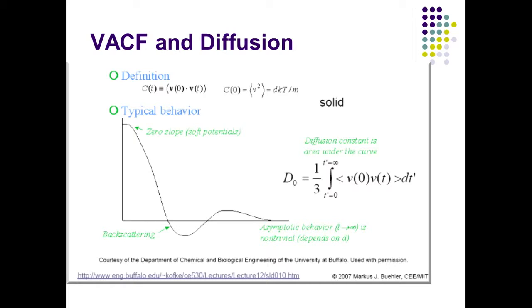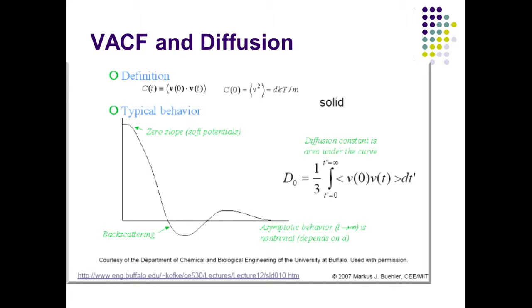As we said, in a solid there is some diffusion of the atoms, but around their lattice structure. So, there is a lattice position, and if you look at X-ray diffraction of the material, you will see particles at particular locations. But you know that at any temperature, given the vibrational frequency, the atom is moving around its central position, and that is the local diffusion. So, you can also calculate that diffusivity in the solid phase within the crystal structure using the velocity autocorrelation function, while the shape of the velocity autocorrelation function, which we call the time tail, gives you the idea that it is a solid.